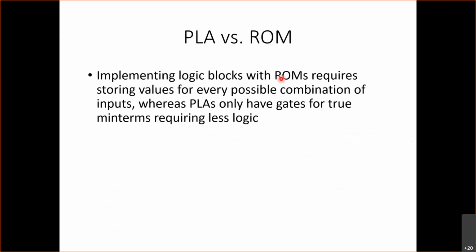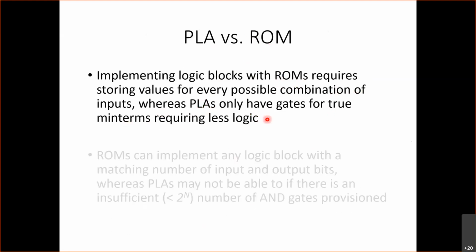Implementing logic blocks using ROMs requires you to store a value for every possible combination of inputs. On the other hand, with a PLA, you only need logic gates for the true terms. So this requires less logic.